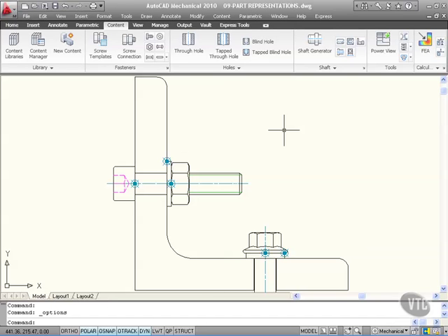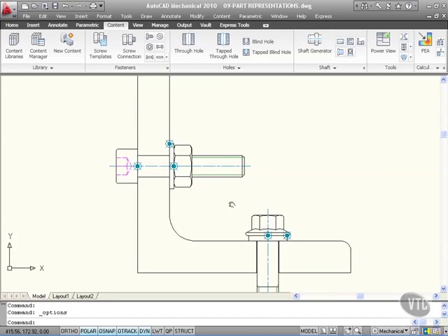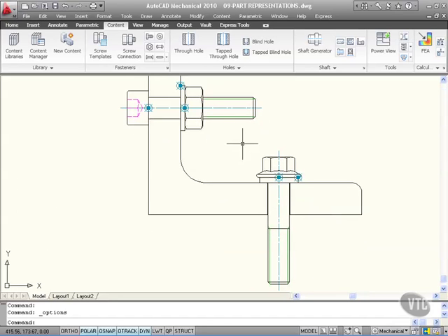When you're working in AutoCAD Mechanical, there are three standard part representations. They are symbolic, simplified and standard. Now at the moment we're using the standard representation. So these nuts and bolts here and everything are using the standard representation. You can change the default setting for that, i.e.